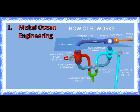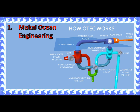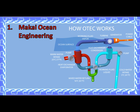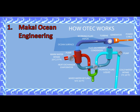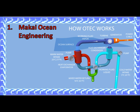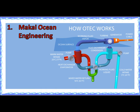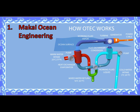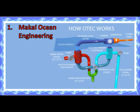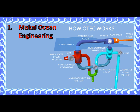Mackay Ocean Engineering closed-cycle ocean thermal energy conversion works like this. The working fluid liquid is being pumped into the evaporator. Using warm water intake, it will vaporize the working liquid. The working fluid vapor will go to the turbine to generate electricity, and the working fluid will go to the heat exchanger condenser. Using the cold water intake, it will condense the working fluid into liquid, and the cycle goes on and on.